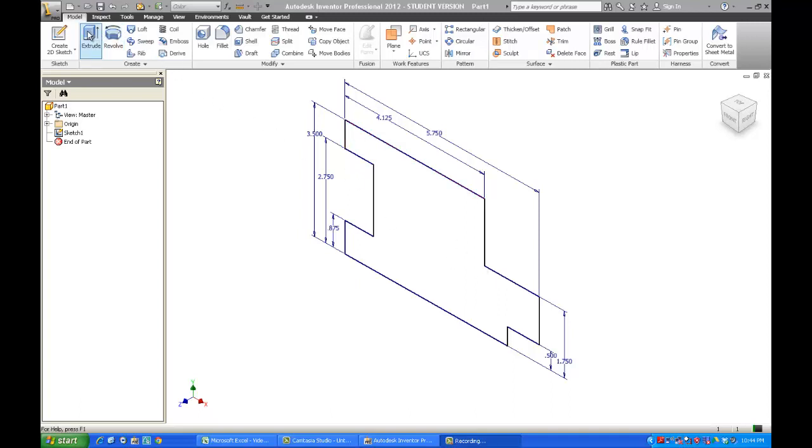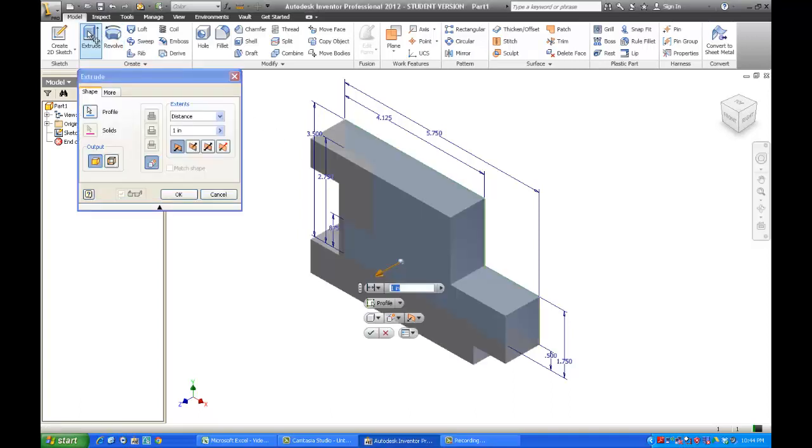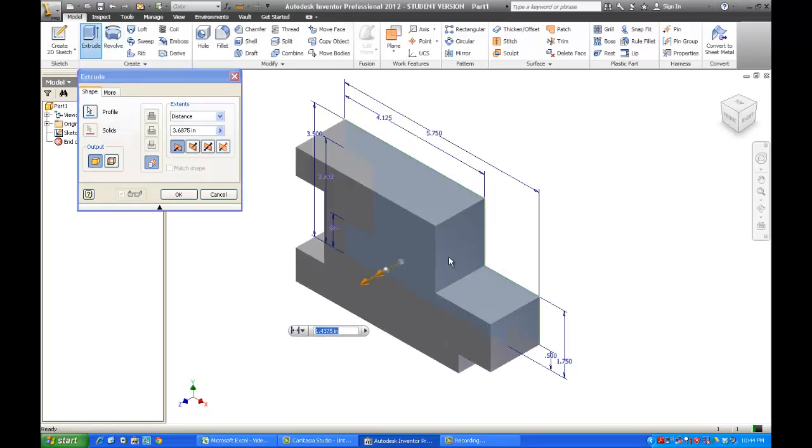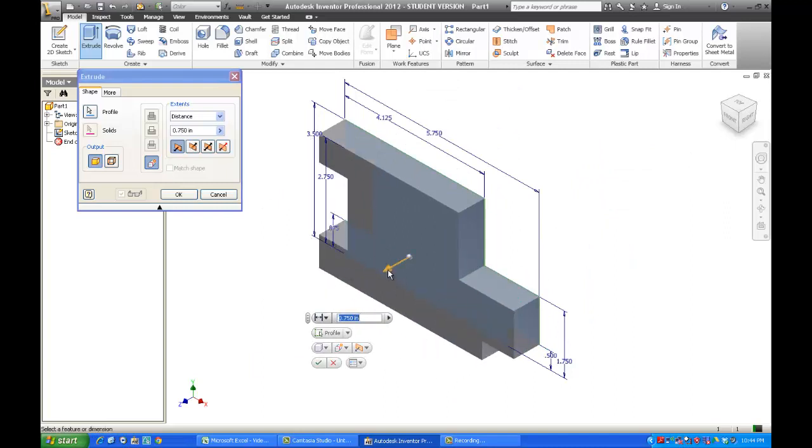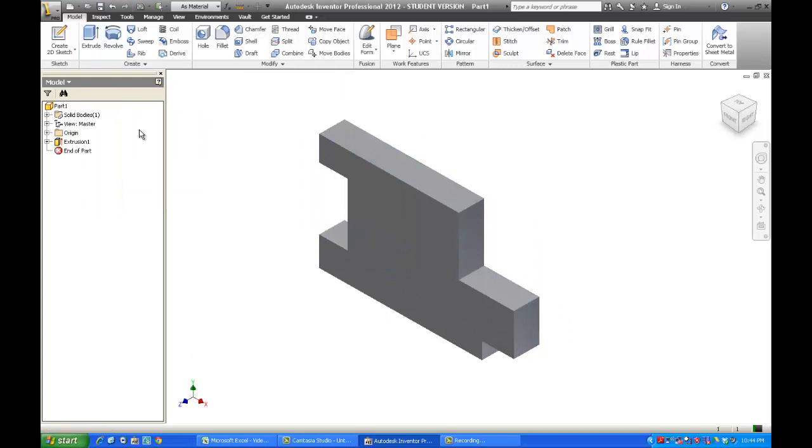The first one we're going to show you is extrude. Extrude's really easy. It does exactly what it says it's going to do. It stretches the part in the third dimension. I can go forward or backward on my plane, and I can specify a distance. Right now, I just take the default forward, and I'm going to let it go 0.75 inches exactly forward. There. That's all it really takes. That's how extrude works. So let's show you a couple other tools that go with this.